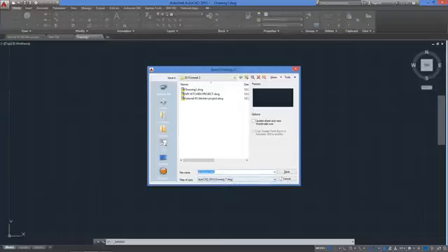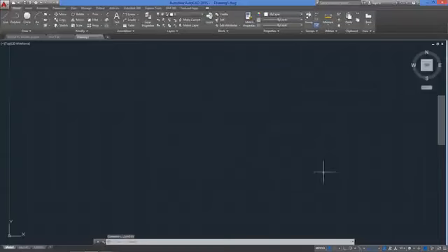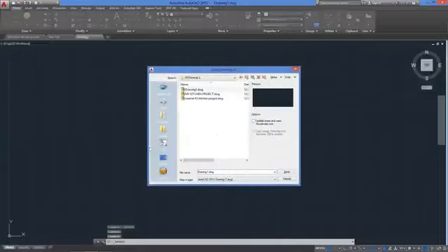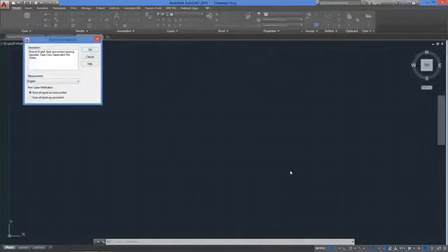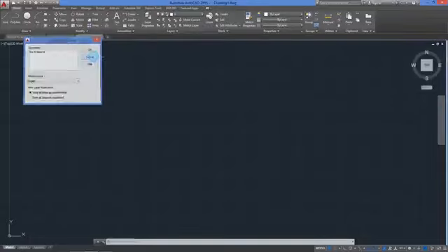On the other hand, we are encouraged to create our own template if we need it, and it should include everything that can be used repetitively in a drawing like blocks, dimension styles, layers, symbols, etc. And of course, we'll come back to this subject later on when it has some more meaning for you. For now, you can save a template just by selecting the DWT format when saving, and you can see that it even gives you the option to specify a description for it. Of course, this is optional, but you can use it if you want to.